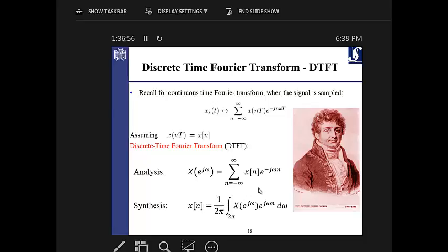This minus here, I see that some of you might be confused with this minus. In the mathematical form, when you want to construct a signal based on the basis, that basis should be multiplied in its conjugate form. And the conjugate for the exponential term is nothing but minus. So the basis conjugate, which is the conjugate for the exponential term, is nothing but minus. That's all. But you shouldn't be confused because of that. It's just the basis times scale. That's all. The value of the signal.